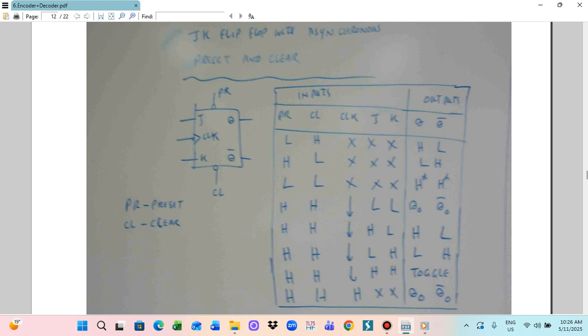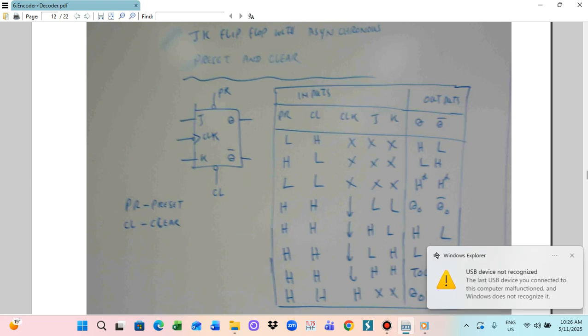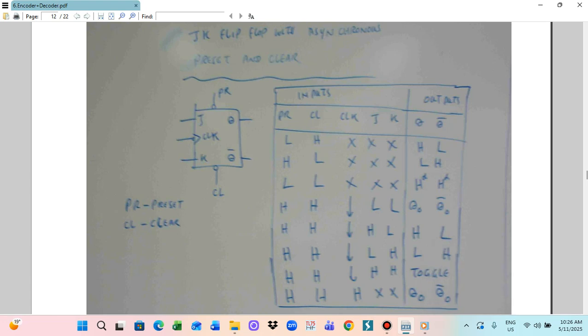So the JK flip-flop as an asynchronous flip-flop. Asynchronous means a preset and a clear state. Sometimes when we are working with the flip-flop, we not only give the data input, we also need to clear the state, clear the condition, because sometimes you work on the initial condition, and after that you need to clear all the initial conditions. So in this case, we utilize the asynchronous preset and clear. The asynchronous preset and clear functions need to be provided for the flip-flop.